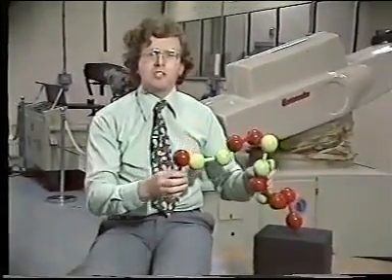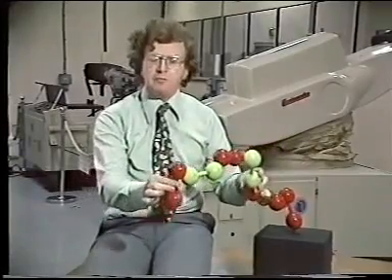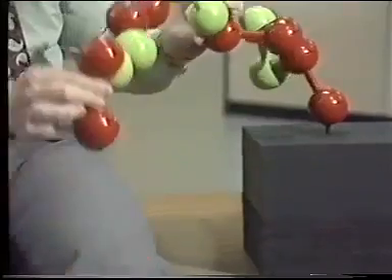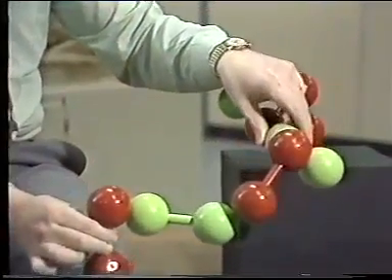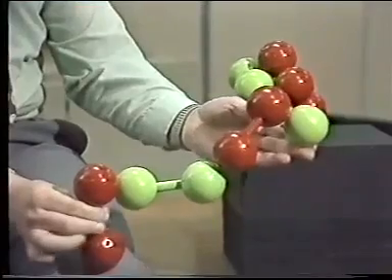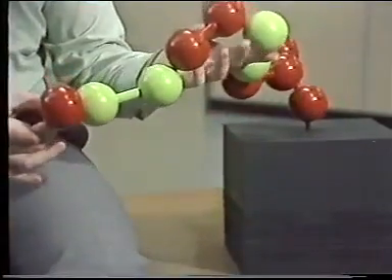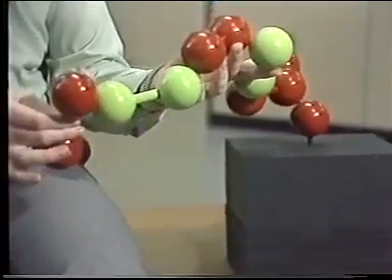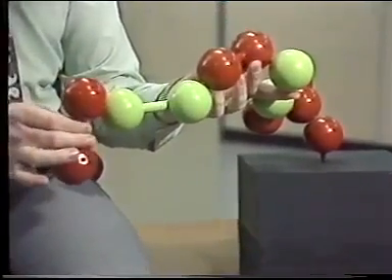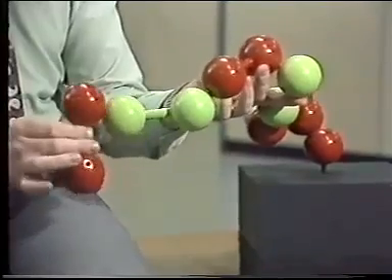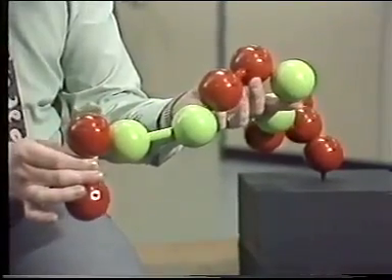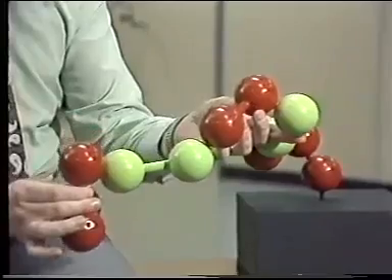Let's just go back to Joe's model for a moment. This is the one, you remember, that had all 6 degrees of freedom. And for a given position of this end link there, say, there's one configuration, and by moving it a little, I can easily find an alternative configuration for the same position of the end link. And in fact, there are several more. This model has very general geometry. All the axes are skew to each other. And that's what makes it so very flexible.